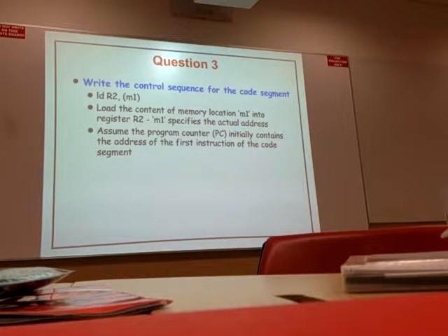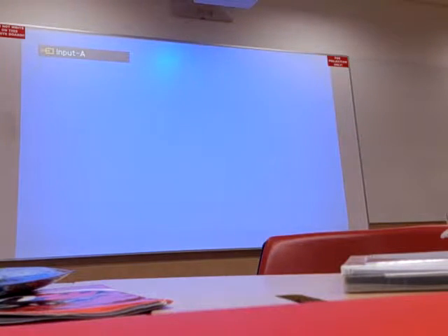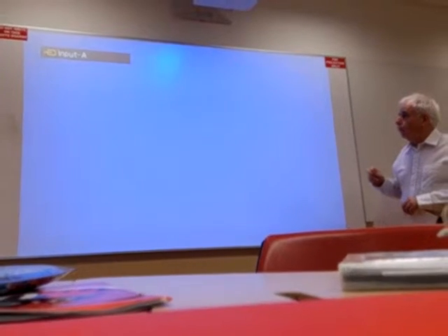Load PC, load only? Only ALU? External to program counter, go to instruction register, instruction register to decoder, decoder to memory address. Then for memory data to come back is 4, then go back into the register.